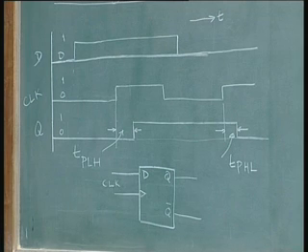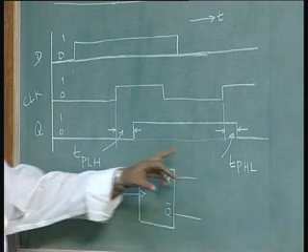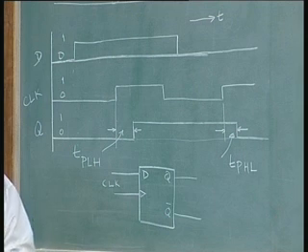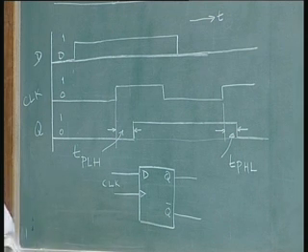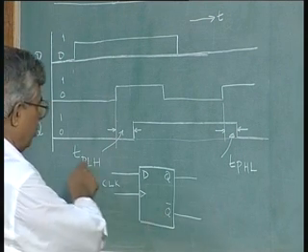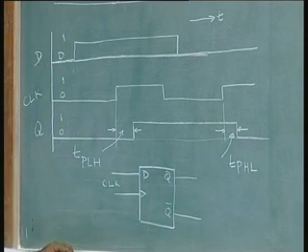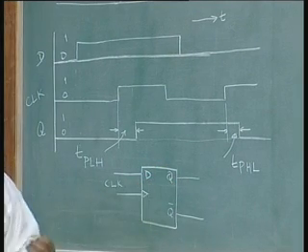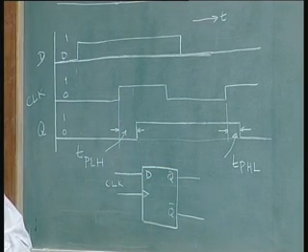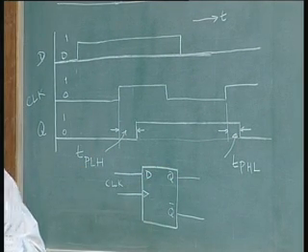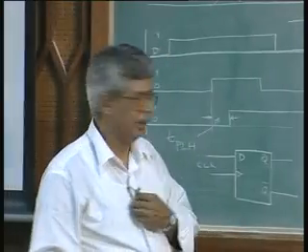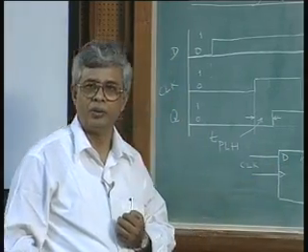Now, when you are talking about flip-flop transitions, generally for typical values you will take the average of these two. In some cases we will take the maximum of these two, depending on the type of operation. So, worst case delay is the maximum of these two and typical value is the average of these two. This factor is important, that you should know before finding how fast, how frequently you can clock the circuit. Before you can decide that, we need to know these values.